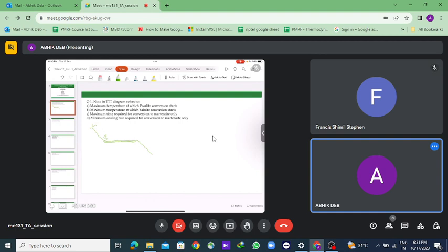So that part is actually called a liquid shrinkage, isn't it? S2S, this is the solidification region. I am not understanding what you were trying to say. Different books will have different terms. This is basically the phase change. During phase change, if there is any change in the volume, like from liquid to solid, that is the solidification shrinkage. That is whatever happens during the solidification.